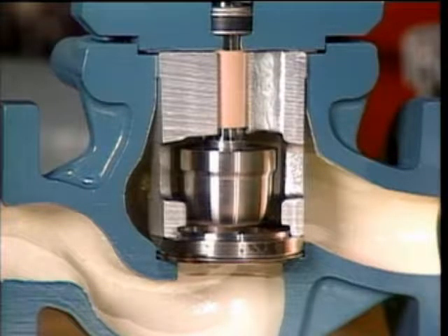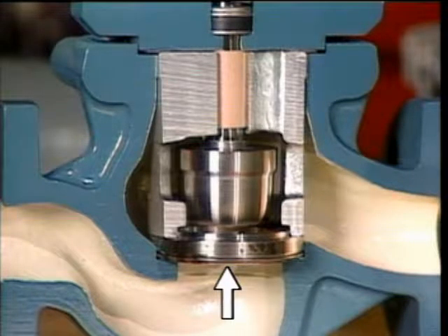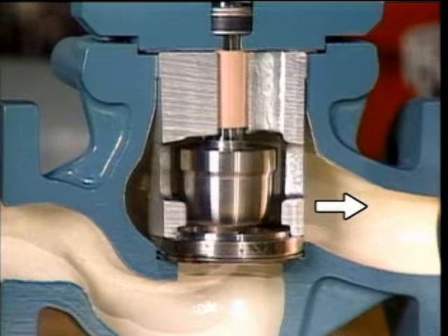The cage is a hollow cylinder containing openings. When the valve disc is moved away from the seat, fluid flows up through the seat, through the cage openings, and out of the valve. In this topic, we discuss general classifications of actuators and what type of power each actuator uses to move a valve. We also looked at the function and design of control valves.